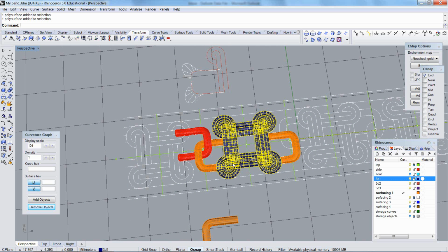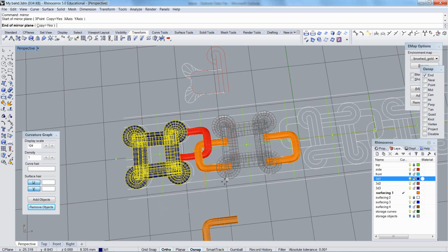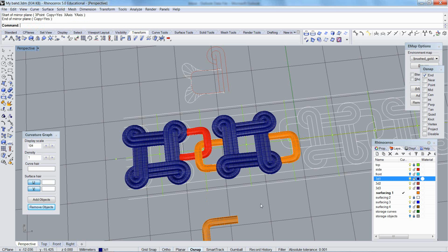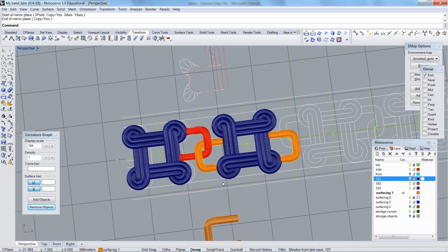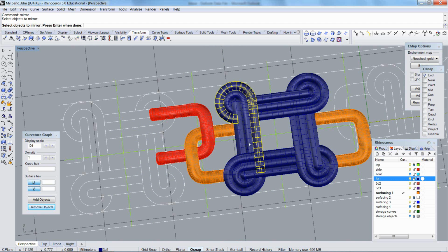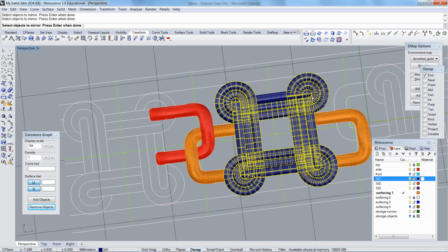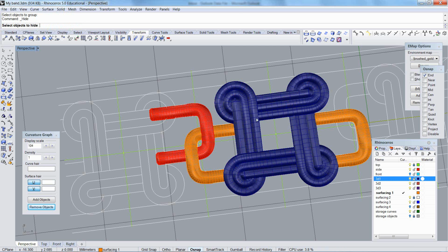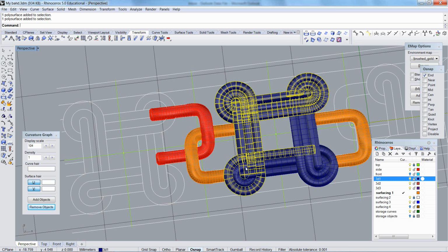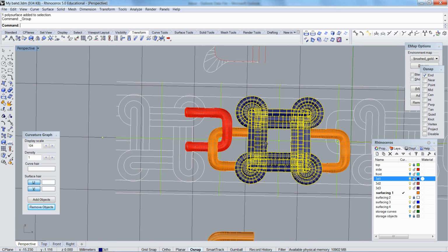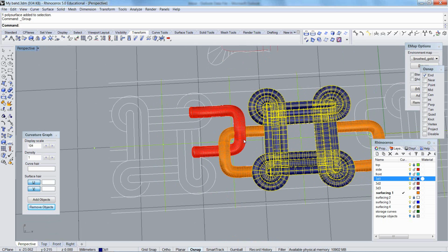arrange it. Now in my design's case, this is actually a mirror from side to side. Somehow I got that wrong. I am going to group these. It's important to remember what you've grouped and what you've not grouped, because you might be clicking on this and thinking you've booleaned it, and you haven't. These are only combined for purposes of selection.